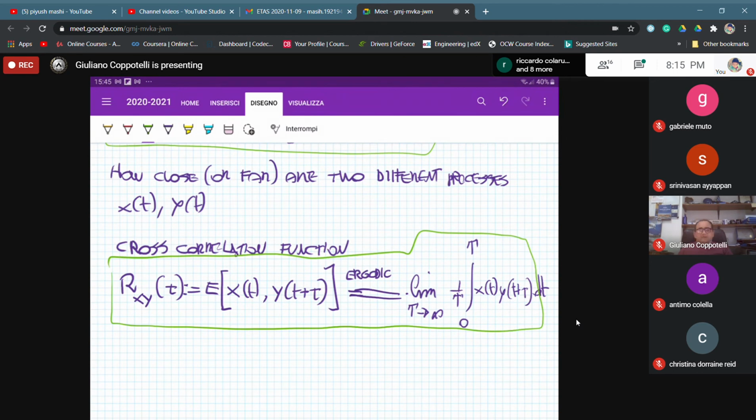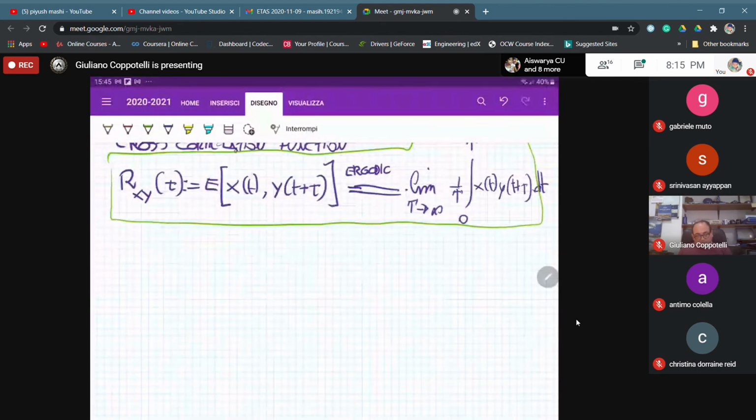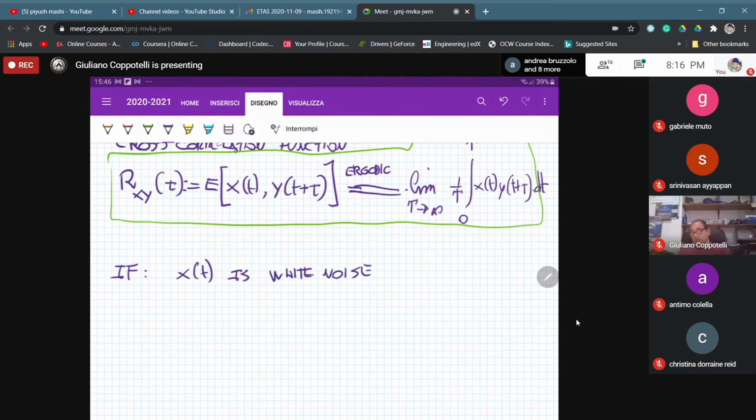Just to give you an idea, let's consider a process that is characterized by a Dirac. If your ergodic stochastic process is white noise, then, as I told you before, the autocorrelation function is k times the Dirac. What does it mean?